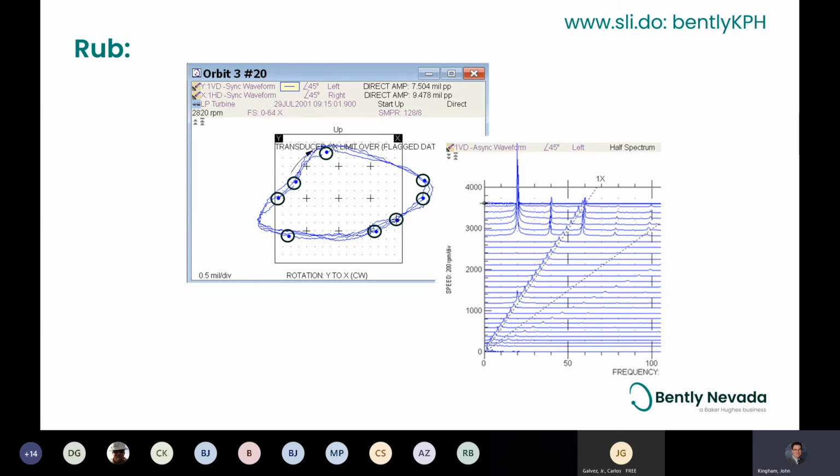And now note that once the rotor starts impacting or rubbing, it rings that frequency. And that's why we always look for horizontal and vertical relationships in cascades. You'll also see some 2x and some 3x of that 1200 CPM frequency. And I think that's due to the squaring off, because square waves often give you those 2 and 3x multiples. Okay, so that's that.